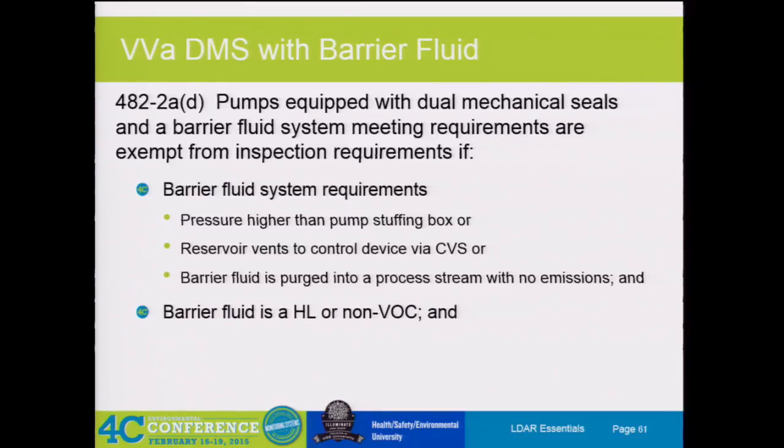Barrier fluid, though, has to be a heavy liquid and non-VOC. A lot of people use just regular turbine oil, or Royal Purple, I think, is the other one that I've seen out there.